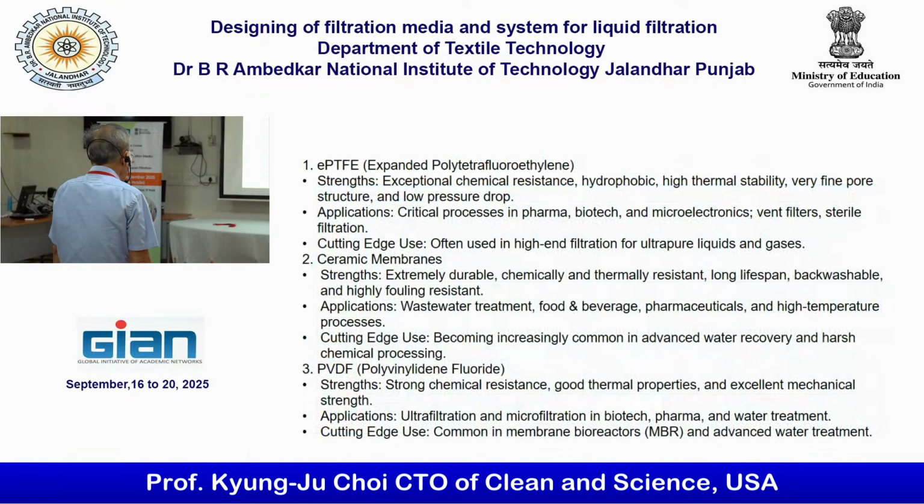So, the expanded polytetrafluoroethylene strength is exceptional chemical resistance, hydrophobic, high thermal stability, very fine pore structure, low pressure drop. It has everything, a good one. See, application: critical pressure, pharma, bio, they already use it. Even in the HVAC market, slowly the EPTFE is replacing some other polymeric material or glass material. Cutting-edge use often in high-end filtration, ultra pure liquid and gas.